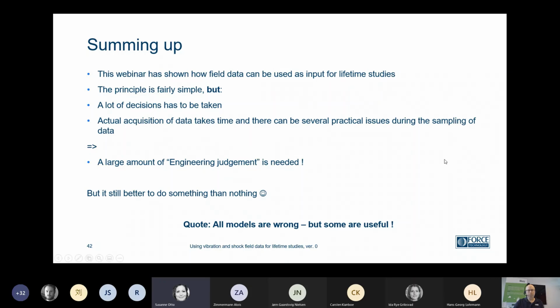David Richardson, yes, thank you, has asked the question: how are you verifying the data are stationary and ergodic, meaning well representing the whole, to ensure the PSDs are valid during your testing? I look at the data generally, and if there are changes where I can see that it's not the same PSD, we typically use the normal distribution of the acceleration. And if I see there are differences, I basically split it up and say I have one situation where I have that PSD and another situation where I have the other PSD.